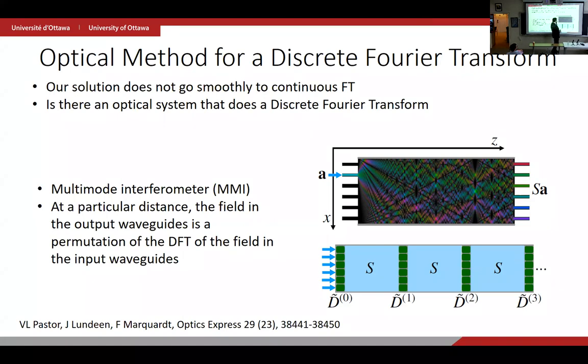Because you're coming in at a particular point, and then imagine you have standing waves, right? Those are going to define the spacing here. That's independent of A. So you have to choose the spacing to match something to do with the width of the waveguide, and you also have to choose the length to be the correct length, which is half of the full self-imaging length. Then there are other lengths at which you'll get any other integer number of points.